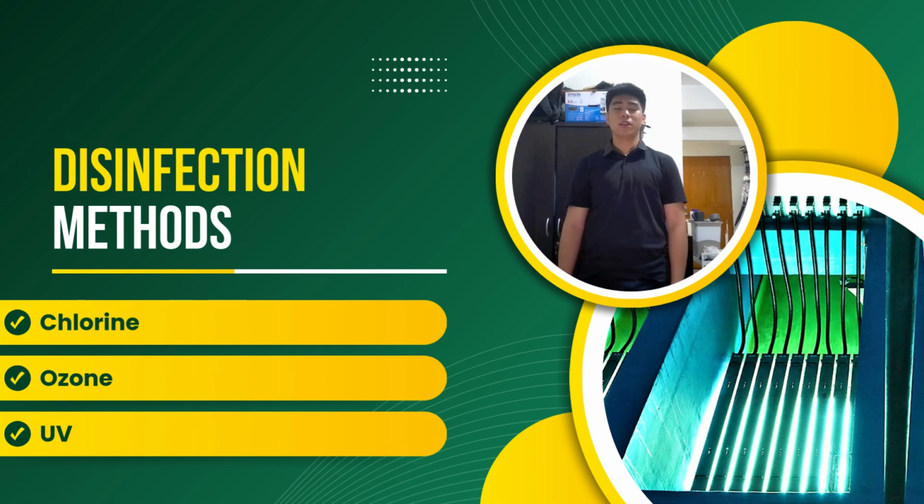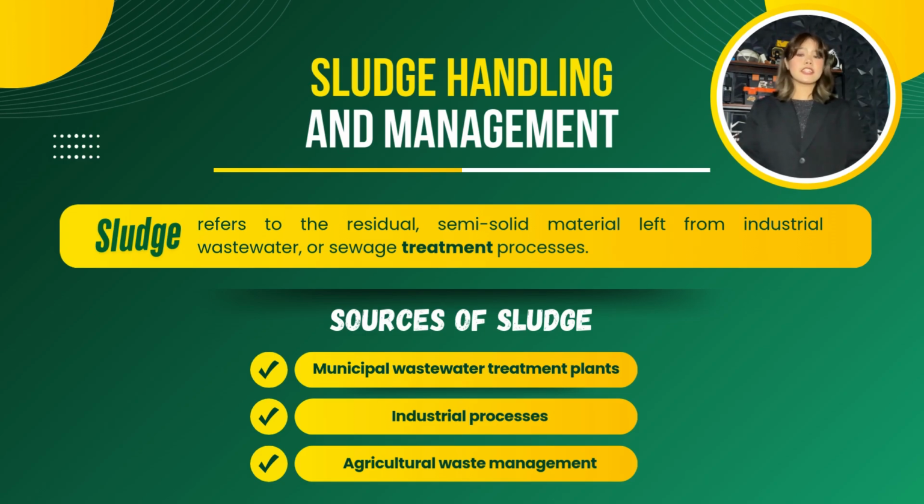Ozone is able to kill off any bacteria and microbial contaminants because it is a strong oxidant. This method works by adding an electrical current to the water in order to turn the O2 inside of the water into ozone. The third method is through the use of UV. UV works by scrambling the DNA of the bacteria. Rather than killing the contaminants, it instead sterilizes them. This still prevents the contaminants from either harming your body or multiplying inside of your body.